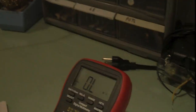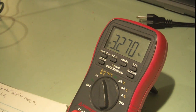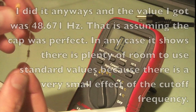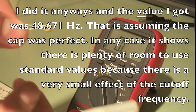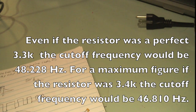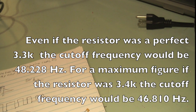I'm going to zoom in on the multimeter here, and it's going to measure the resistance, 3.27. Okay, so we're really doing 3.27. Now I'll re-go through the formula, and I'll leave you guys to do this: when you make your own, choose your capacitor, measure the capacitor, and then put the actual measured value into the formula. I didn't do that in this case. Find the resistor, find the closest standard E12 or E24 value of your resistor, and then re-go through the formula and calculate it to make sure it's close enough.